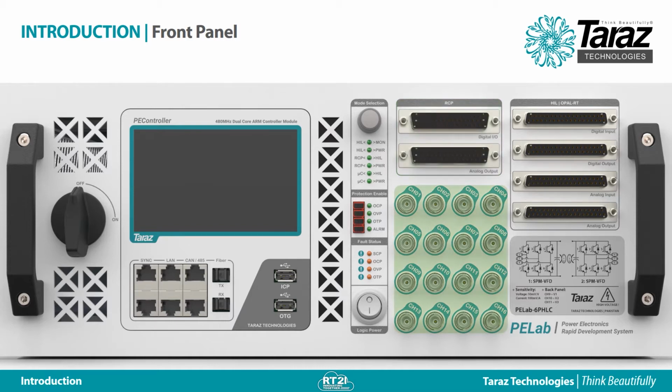The BNC connectors are used for monitoring the system measurements with full galvanic isolation, so you do not need any external voltage or current probe. Also, in HIL mode, the analog signals come from the HIL simulator instead of the sensors. You can find the analog channels mapping and sensitivity information on the label. The mode selection knob is used to seamlessly shift between the different validation stages of the R&D cycle.